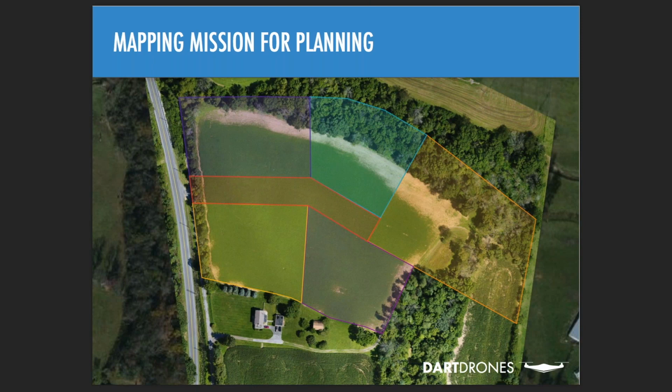So this was in all about a 40-acre total piece that we flew, and just seeing a section of it right here, but able to fly that within a matter of an hour and a half or so on site, max time, get home, upload everything into DroneDeploy, process those images, and very quickly as soon as it was done, just use the tools right there to start hashing out these areas and sharing this map with the clients, so that they could also go in there and play around and move these things around to get an idea of where these lines were going to be.